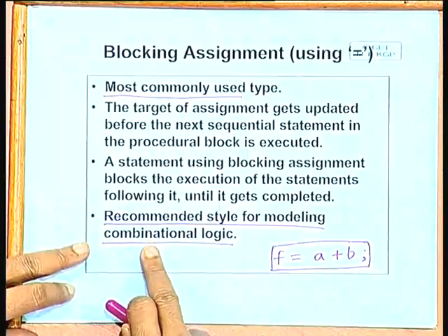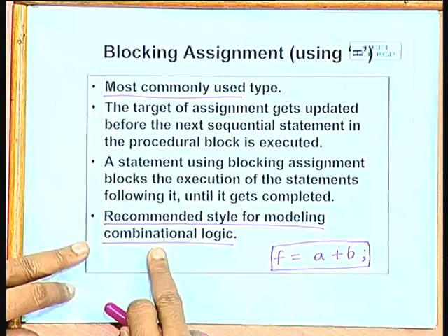But if it is sequential logic, whenever you are assigning a value, we normally do so in synchronism with the clock. Suppose we have an always block with a positive edge, and inside the always block there are 10 statements. What does that mean? That every time there is an edge of the clock, these 10 statements will be executed one after the other? Not really. The semantics say that at the edge of the clock all the statements have to be executed together. So when you are modeling sequential logic, there has to be something else.